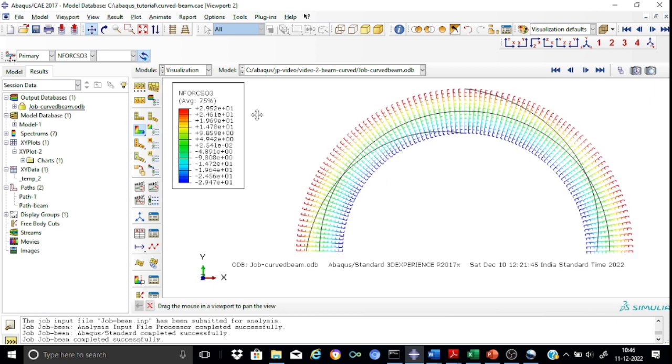Now, if you see the variation, you can say that we have three critical locations for the shear force: one at the two supports, and the other at the interior support. We expected the same result. So now we would like to know what these magnitudes are.